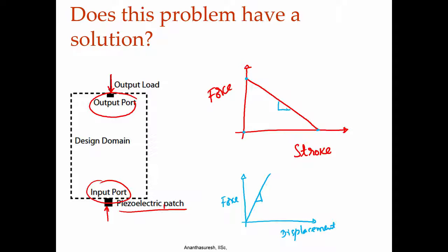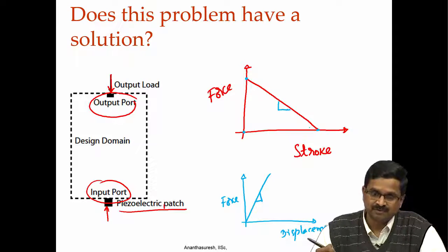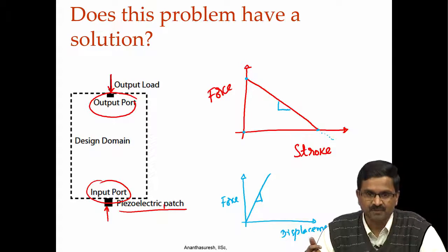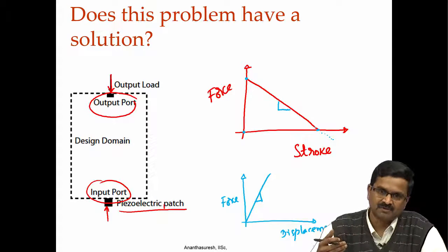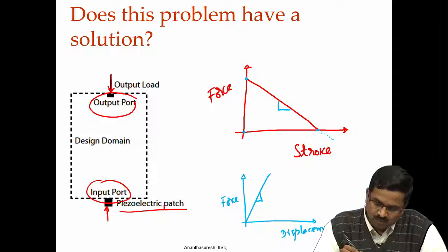That is the meaning of an actuator actually. Looking at it, it is an actuator because its slope is negative, it is able to give the force in the direction of the displacement, whereas a spring will offer a force opposite to the direction of the displacement. That is how a linear actuator will be, and beyond a certain point you need negative force, meaning it is not an actuator anymore, you have to supply the force by some other means. So, this is the limit, that is all the actuator can push on some object for that stroke length. So, now what is happening?